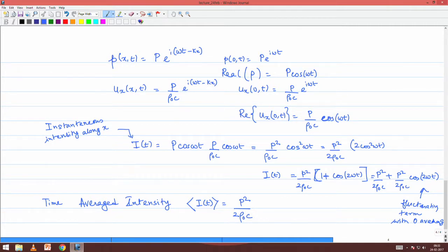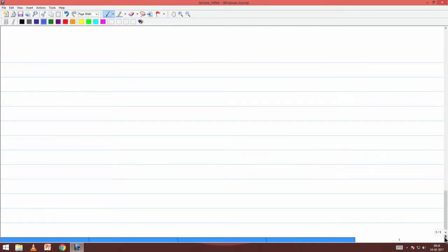Now, what we are saying is that if there is a travelling plane wave, to be more precise, we are actually seeing that there is a power flow happening at any arbitrary section, and a time averaged power flow is there, which is why we are getting this non-zero term, which is P squared by 2ρ0c. Okay. Let us look at another little more complicated example.